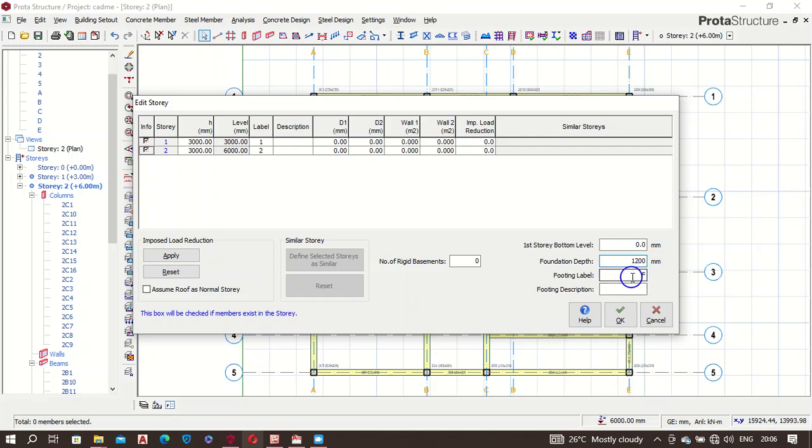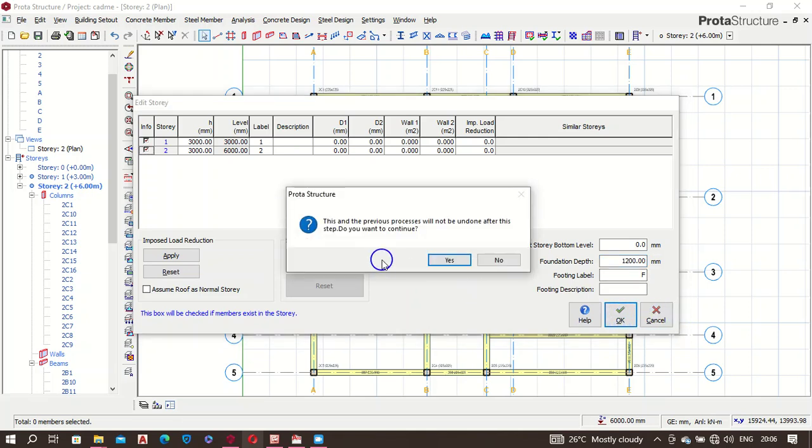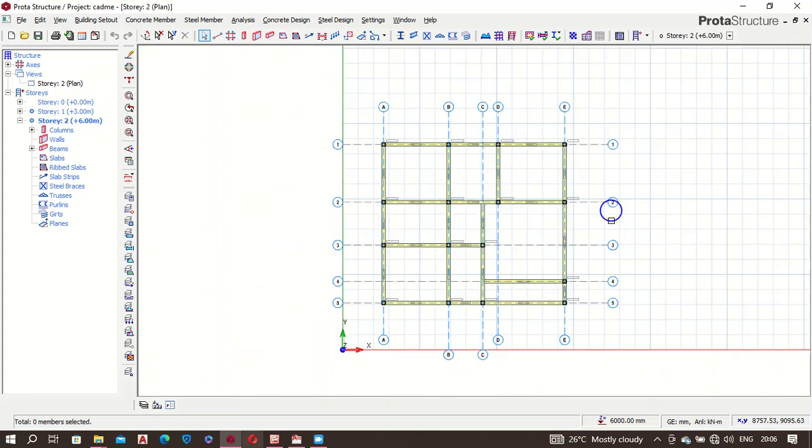You can't just decide the depth of foundation. There has to be a soil investigation, so you can know where you're having a good stratum beneath the soil, where your foundation can sit with minimum settlement. Okay, so we've been able to define that.